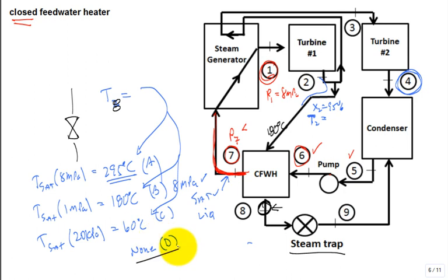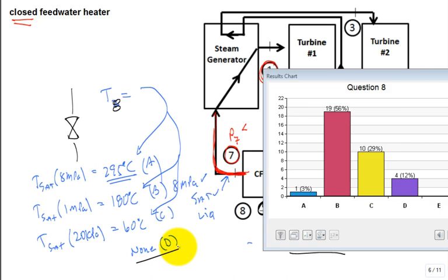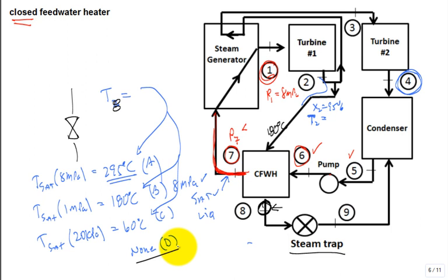The temperature at 8. All right, I'll go ahead and stop. Then we'll show the results. All right, so the temperature at 8 is... Why is it 180 degrees? Because it's saturated liquid and the pressure at 2 is equal to the pressure at 8. All you did was condense at constant pressure, right? When it condensed, all that h_fg came out of the fluid, a lot of heat transfer, and it warmed up.